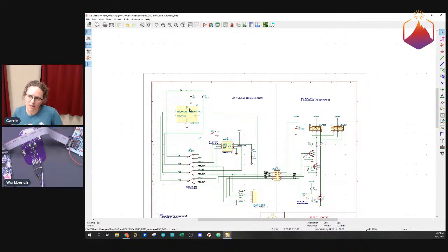But frankly, I'm thinking the people that are going to be interested in this aspect of the board are going to be more advanced people that are probably totally fine with unsoldering and resoldering a SOT-23-6 part, which is small, but it's not impossible. And the parts themselves are cheap, so you don't have to worry about saving that processor when you remove it. You can just solder blob the whole thing, wipe it off with your iron and throw it in the trash, no big deal. Or you can save it, whatever.